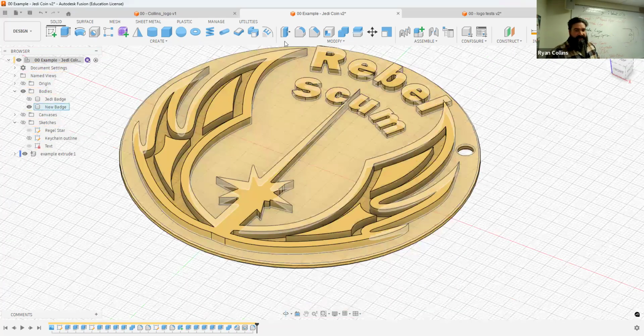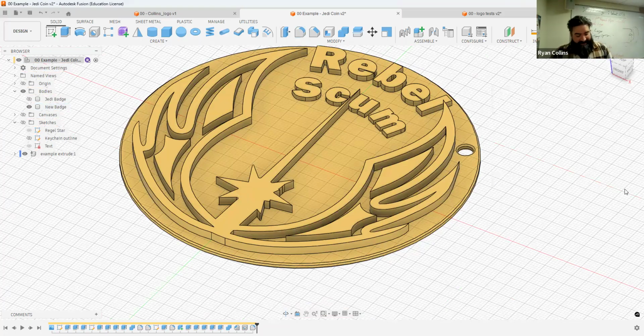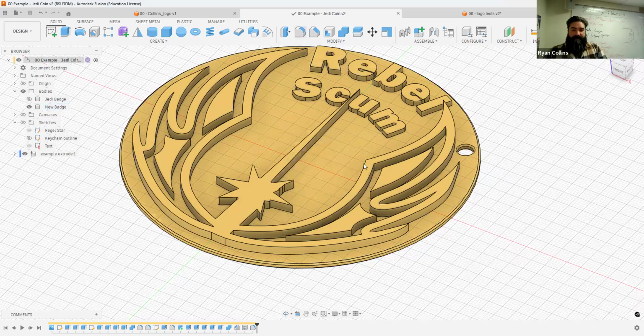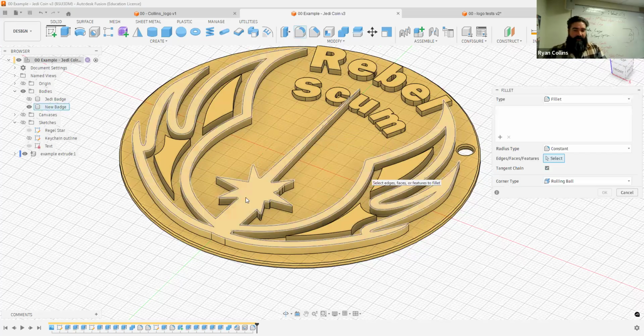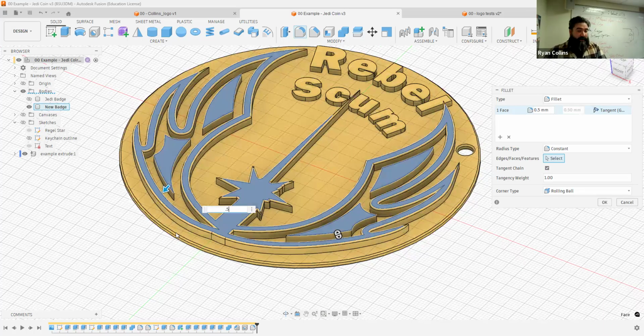So around in here, let's say if I wanted to try this out, I don't know if this will work. Tell you what, let's save. And let's try out a fillet on that. Just because I want to see. I can select the whole face. Now, don't go too far because I guarantee it's going to cause an error. So I'm going to put like 0.5 in. Hey, it worked. Anything bigger, it probably wouldn't work.